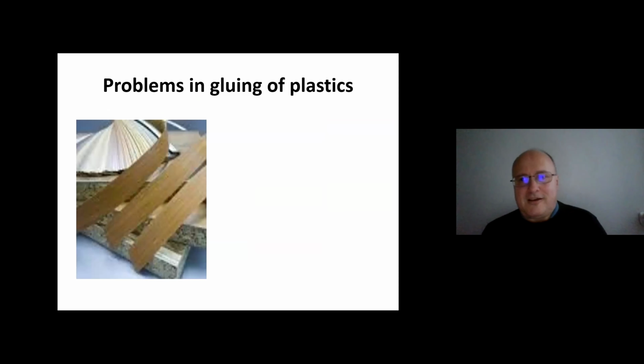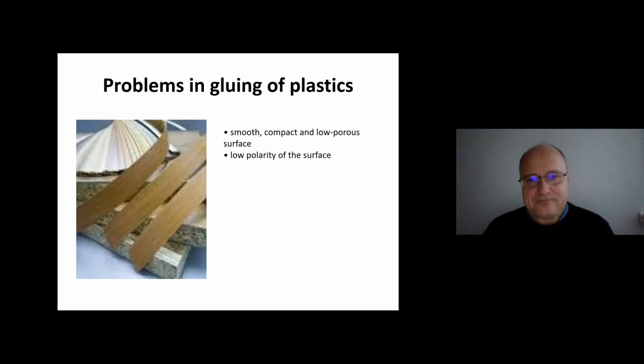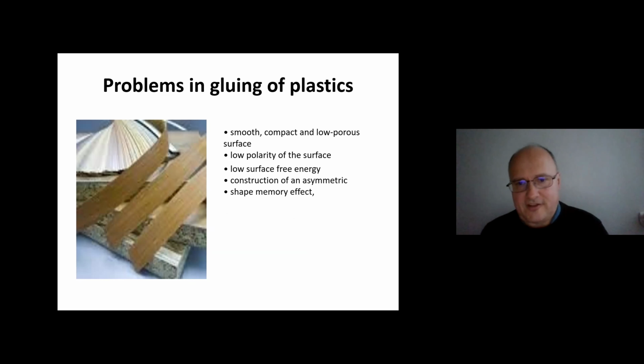And next, going to the engineering practice. Problems in gluing of plastics. There are different reasons. First, a smooth, compact, and low porous surface. Next, low polarity of surfaces. Low surface free energy.